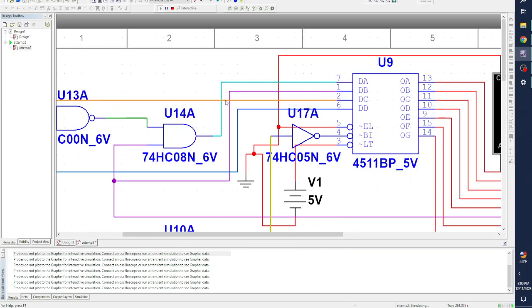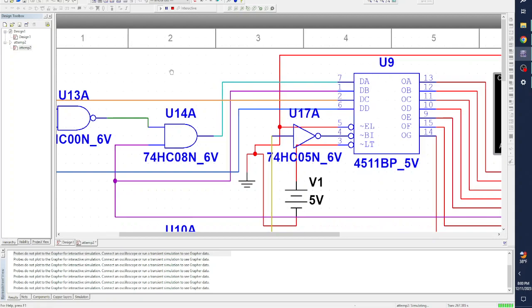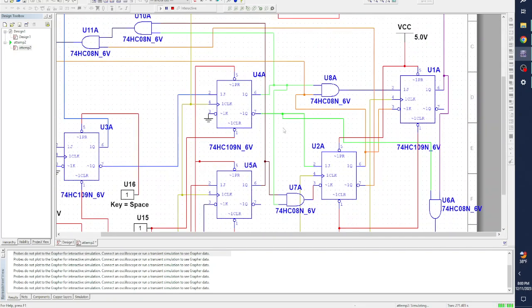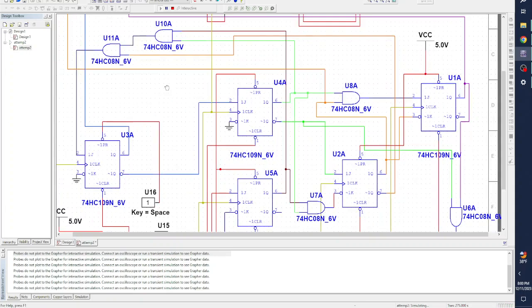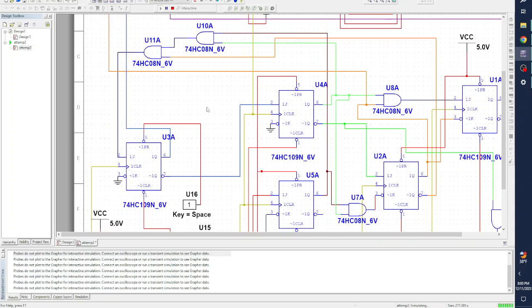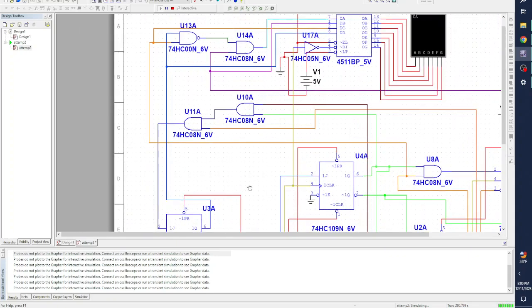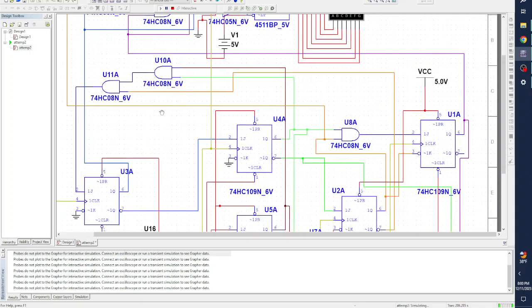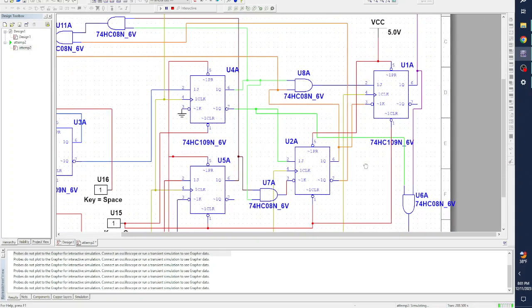So some of the color coding I used for the circuit. First of all, I have this Q0 output in turquoise, and the reason I don't even need a flip-flop for Q0 is because I found that I could obtain it by taking a NAND between the Q3 and Q2 bits and an AND with the Q1 bit to get that result. So that simplified my design a lot.